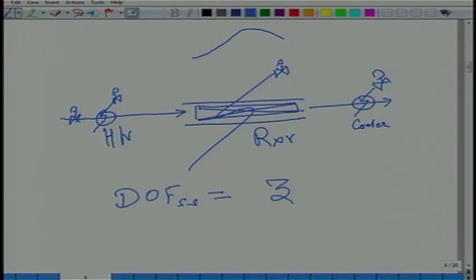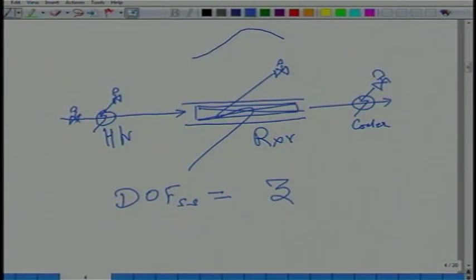What about this cooler? What will this cooler do? It is condensing. So how will you decide whether I need to condense more or less? What did you do in the distillation column? If the pressure is going up, condense more. If the pressure is going down, condense less. Same thing here. Now pressure controller is an inventory controller. Basically, how much vapor or gas is stuck inside my reactor system, right? If the pressure is increasing, more gas is stuck. If pressure is decreasing, less gas is stuck. Yeah, so it's essentially an indicator of vapor inventory. I am, however, counting it. Why?